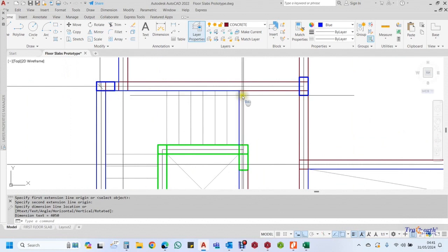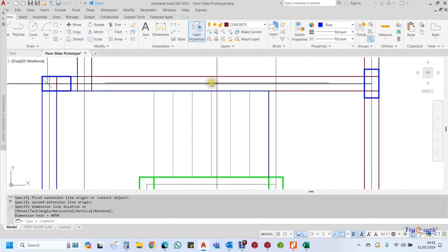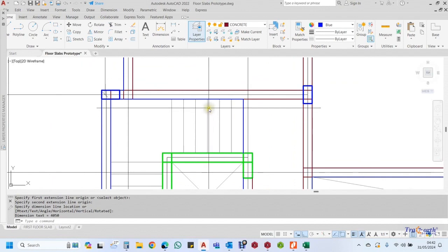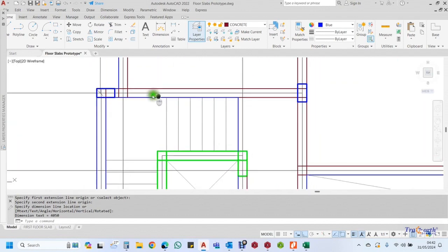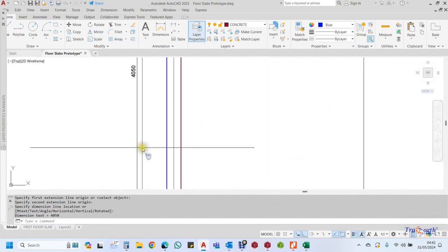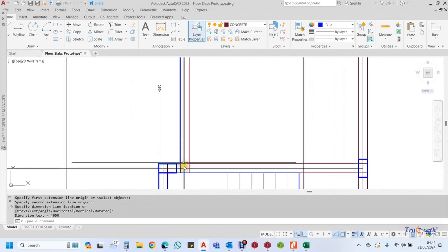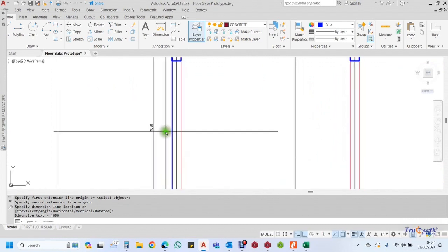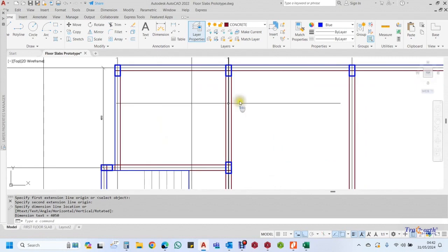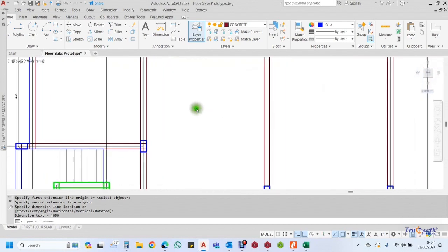So what I'm trying to say is that even though we have a slab that is continuous on this edge, because it's not even covering up to half, we can consider this as what? A discontinuous edge. So the shorter side, the shorter edge, the first edge, we can say this is discontinuous, this is continuous because it's bounded by another slab.